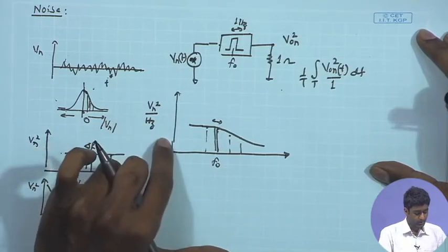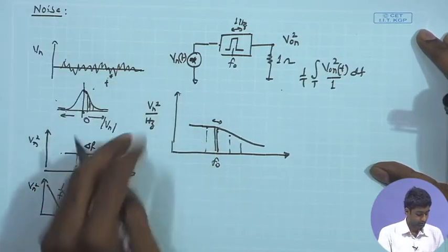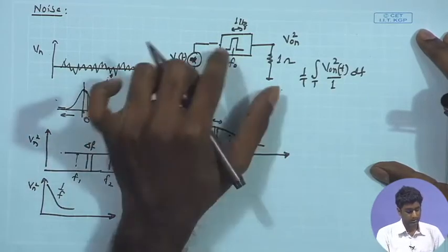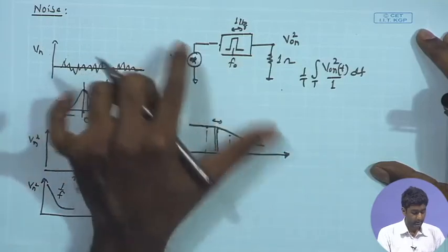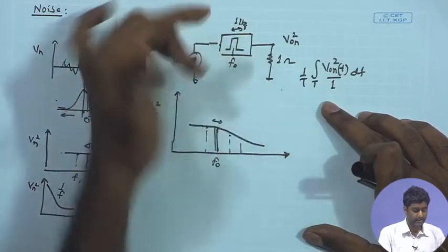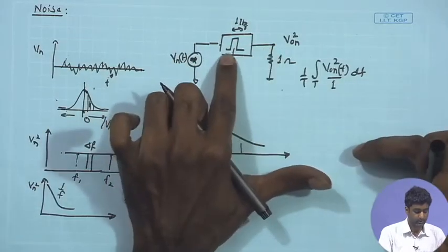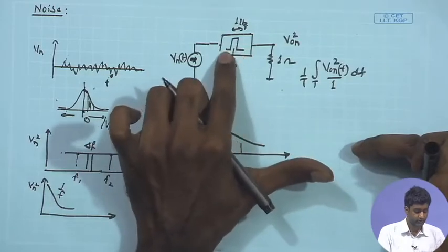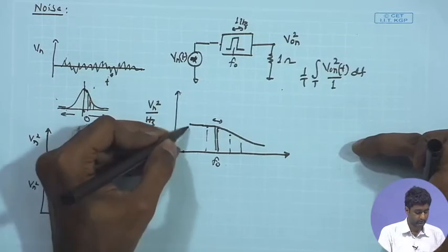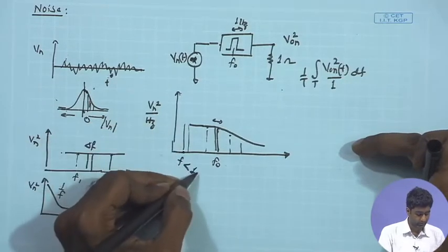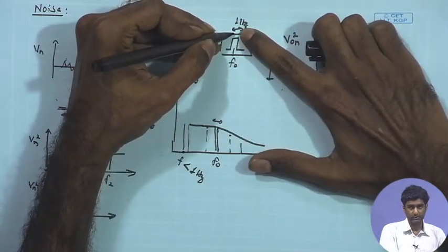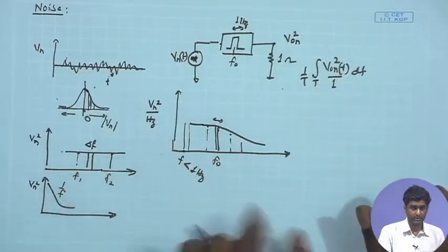Now, if we look at the bandwidth definition over here, I have chosen it to be 1 hertz, and that would mean that you are having the power delivered in this 1 hertz bandwidth, and then you are denoting it as the energy or power delivered per unit hertz. But definitely this definition also has to be valid at much lower frequencies, much lower than 1 hertz. So, if you have to get the spectral density at frequencies f lower than 1 hertz, the only thing you have to envision is that the bandwidth of this filter is reduced, much lower than that particular frequency.